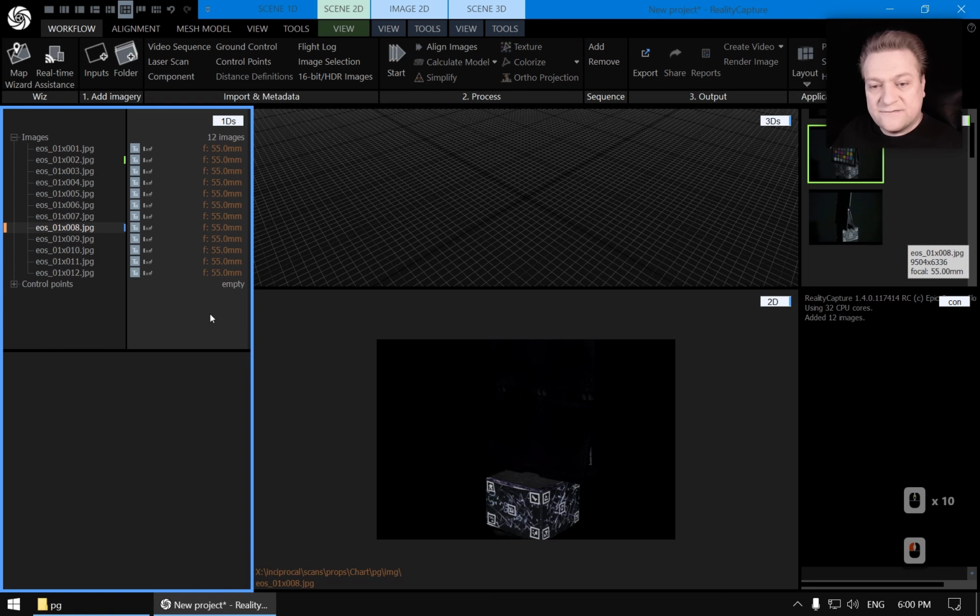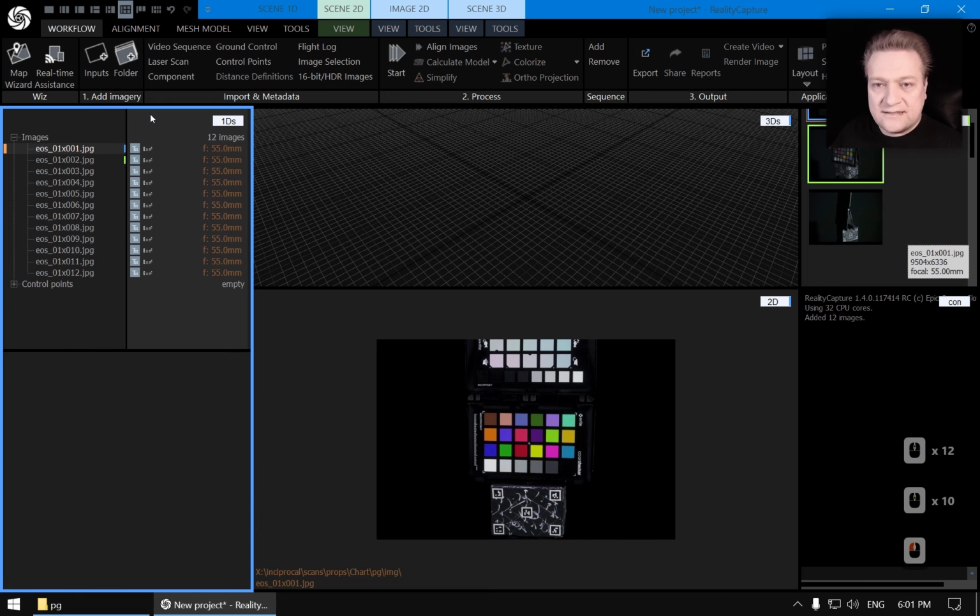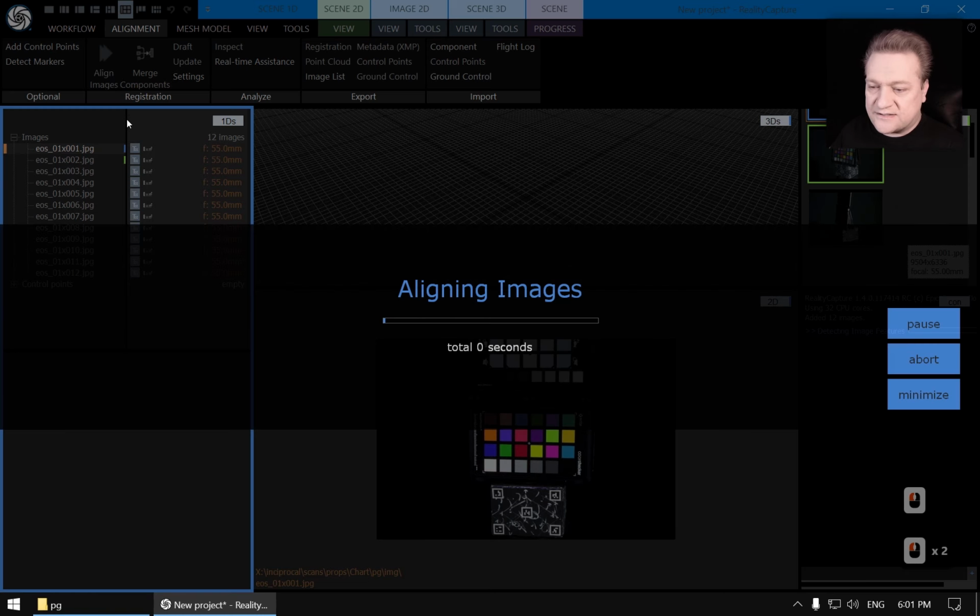And what that tells photogrammetry software is to optimize lens parameters independently. And that's a good thing when every single shot has its own focusing point. But in this case, we basically shot everything in manual mode, manual lens focus, so we know that all parameters should be the same. However, right now, when nothing is grouped, let's go ahead and run the alignment process.